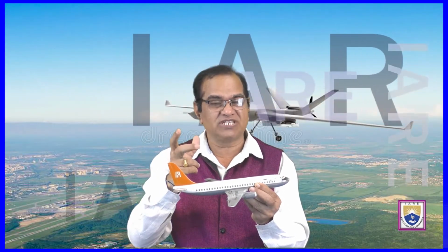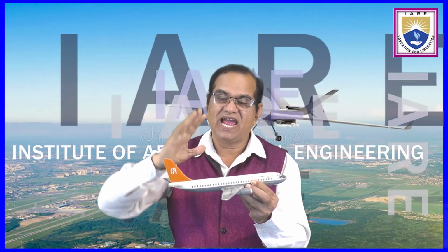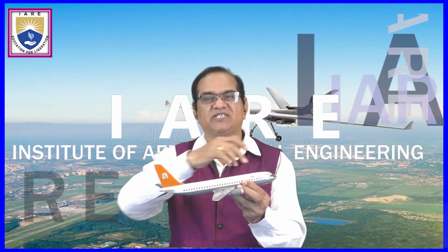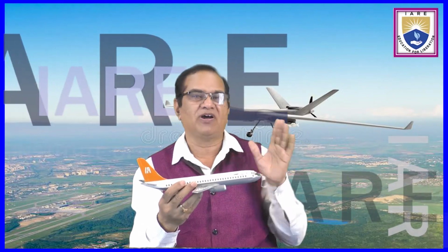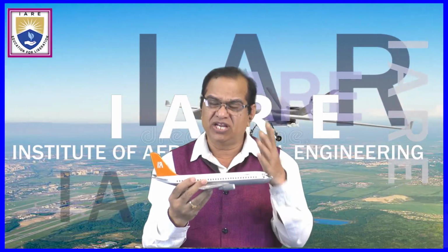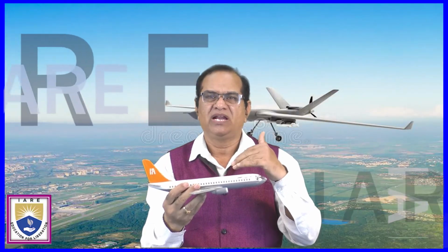So there is a confusion here: the longitudinal motion with respect to the lateral axis, and the lateral motion with respect to the longitudinal axis. And there is a third one, which is called yawing. Yawing happens with respect to the yaw axis, or the vertical axis. In this, the nose will go either left or right. So these are the three rotational motions and three linear motions.